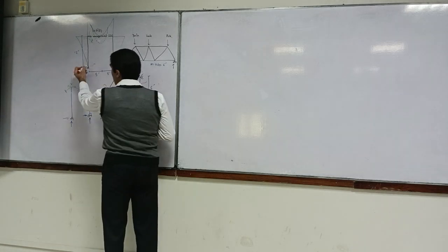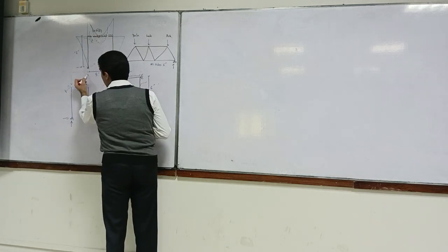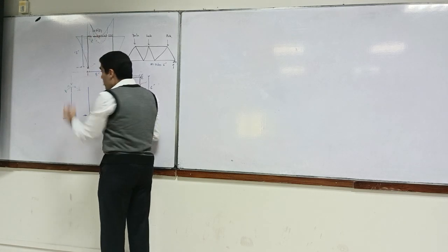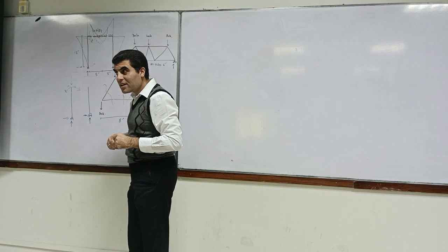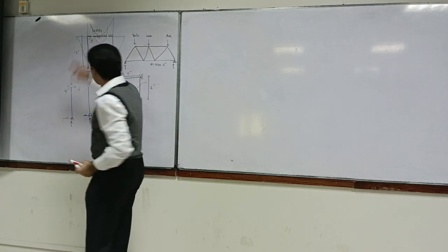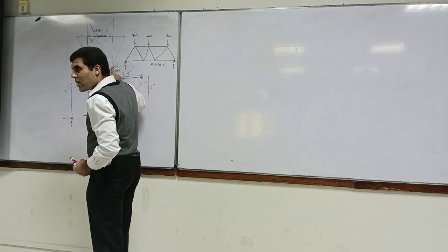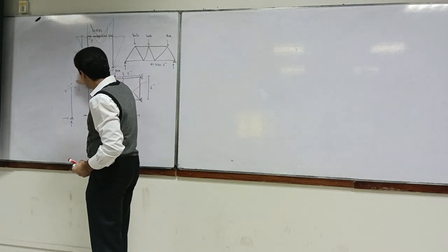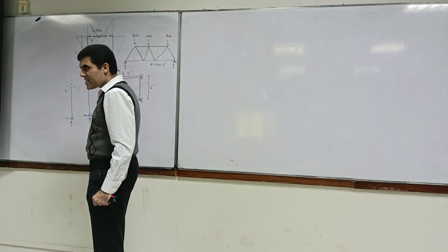You have got a third equation which is about this point. So you take moment of force this time this one and this time that one. So you get this horizontal force. Sir, vertical force is unknown as well. So you can take moment, this gives you an additional moment location. You can have moment equal to 0 at this point and then you can find out your vertical force, can't you? Because the horizontal force above this point is 0, lever arm is 0. Yes, sir. You understand my point?